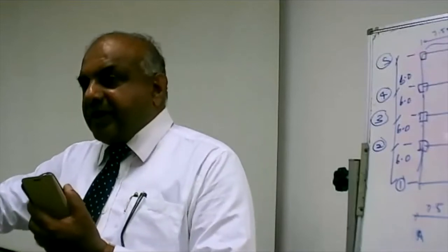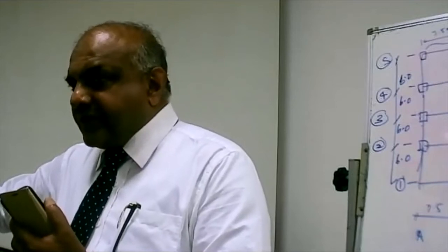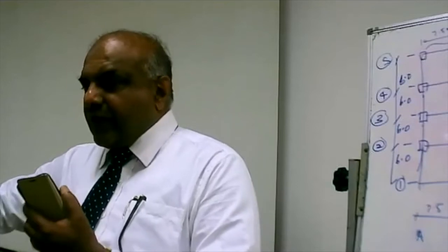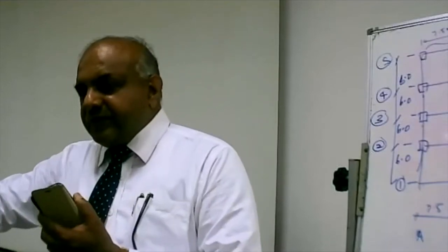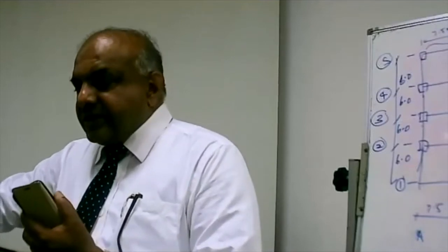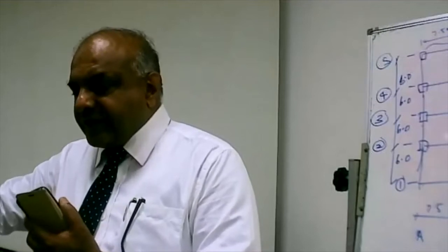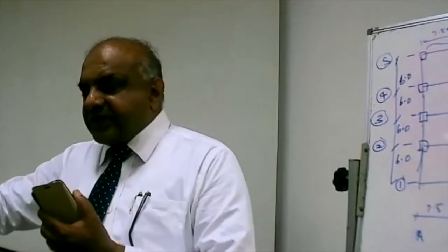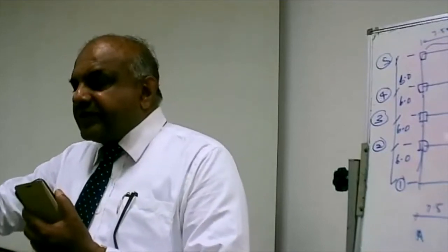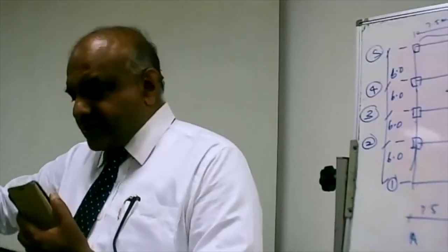But notional load, you don't multiply it by a factor. Notional load is whatever the value you get from the calculation, but you don't have to multiply it by a factor. Whereas wind load, you have to. It's better if you consider notional load and wind load all together. If you are using a computer package, it will automatically select which one is more critical. Otherwise, you have to look at the load magnitudes and decide which one is more critical. It's true that notional load should be used.